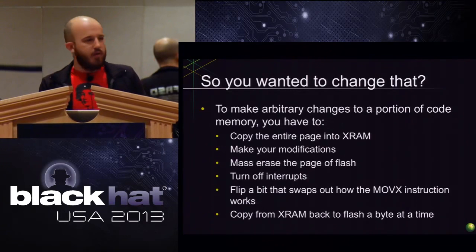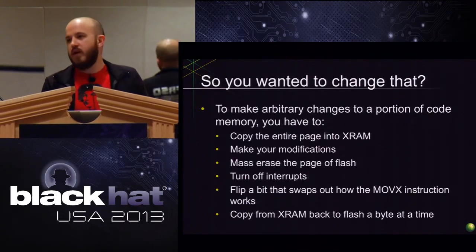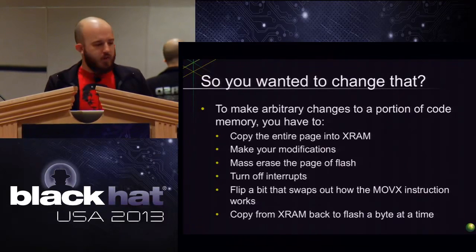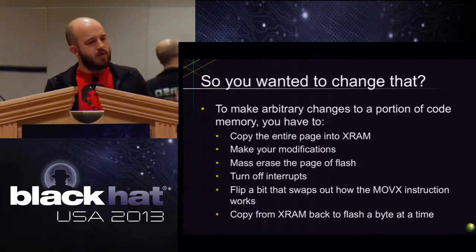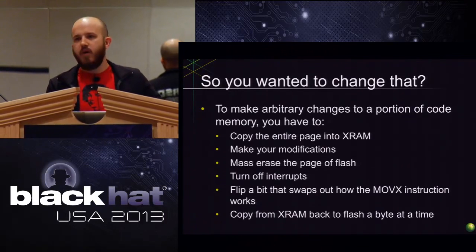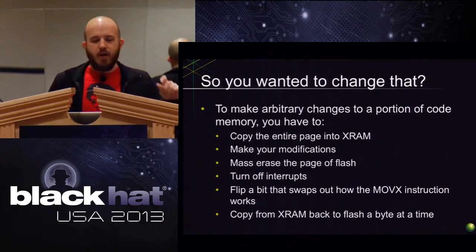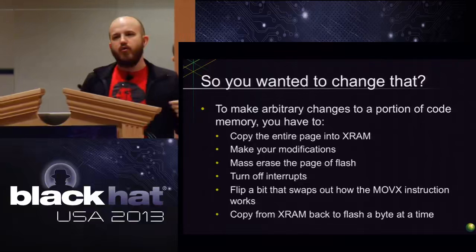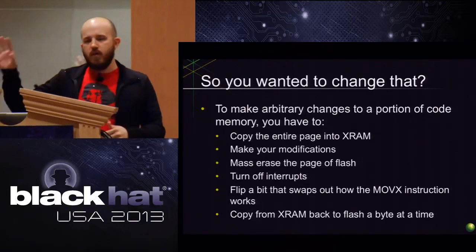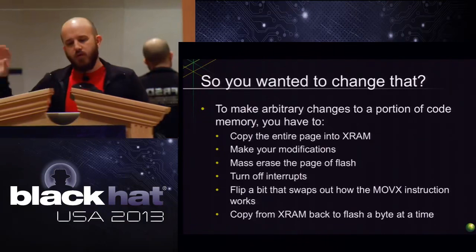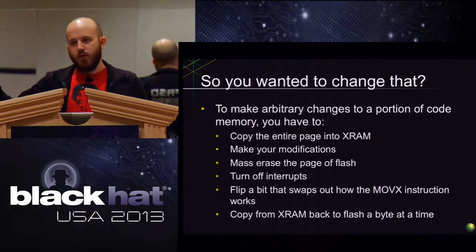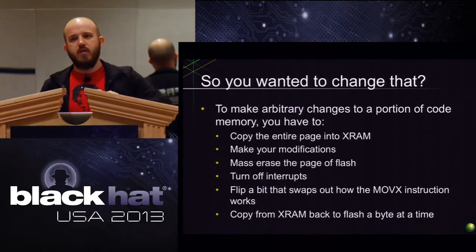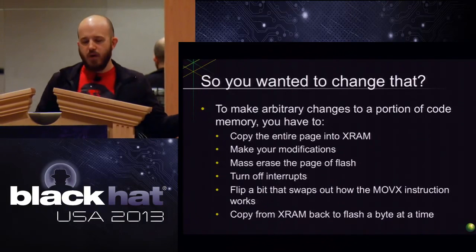The other things you have to do, like I mentioned earlier, you have to make sure you turn off interrupts and turn off CE, things like that, because it'll step on you right in the middle of it. The way this particular Harvard implementation works, like I mentioned, normally you can never modify the code page, you can never modify Flash. There's this movex instruction, where normally it means copy data to or from X data. X data being a very particular section of memory, where all the data is stored, like all your variables and all that kind of stuff, not code. And you flip a certain bit, and suddenly that same instruction now makes a modification to the Flash memory.